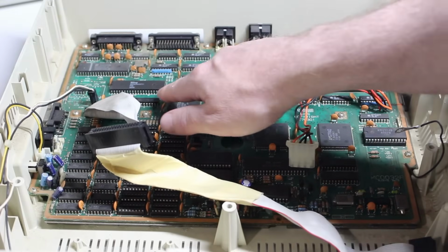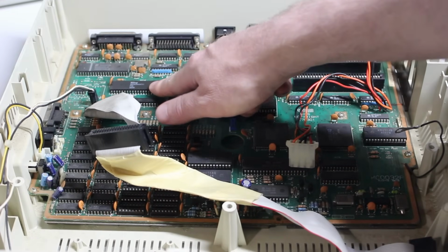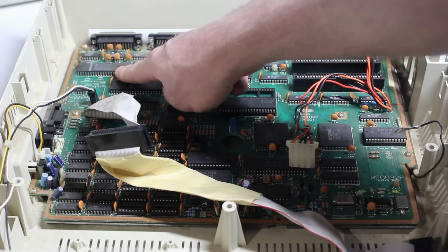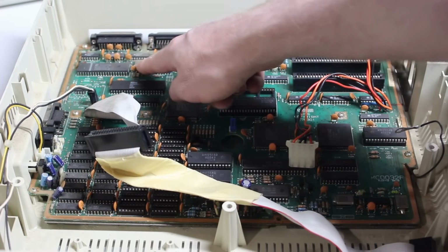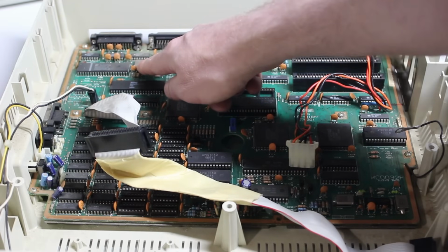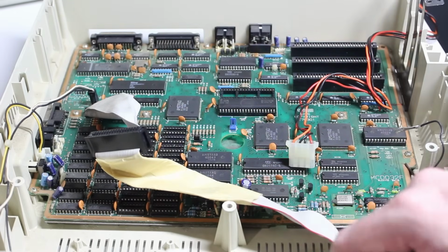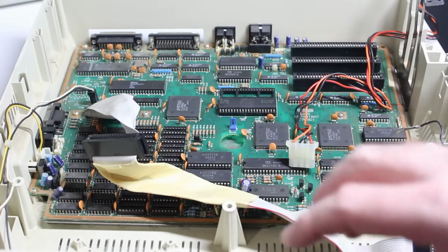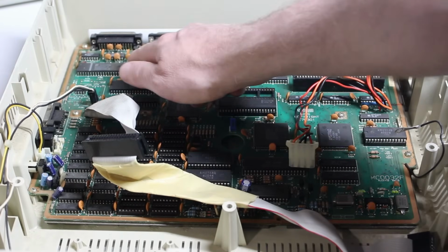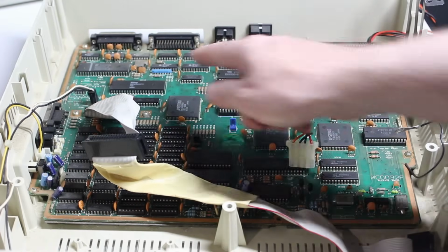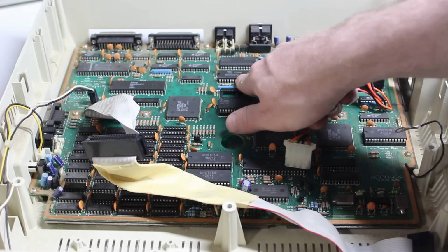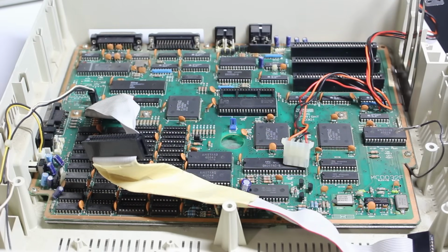Now at the top here we have a Zilog floppy disk controller and an 8250 serial I/O chip, and an interesting crystal, a 1843.2, presumably kilohertz, so 1.8 megahertz. I have no idea what this one does. If you know, let me know in the comments below. Probably that's not going to be relevant to us today, although there is a possibility that it controls the programmable interval timer. Not really sure on that.